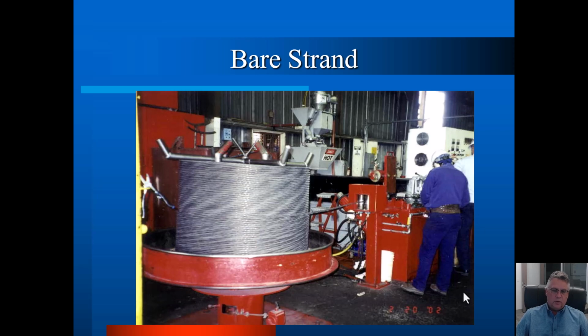So this is the Dywidag Systems International, or DSI, plant in Long Beach. They just need one big, large spool of half-inch diameter strand. And then they will take your drawings and cut to length exactly what your drawings require, the multiple different lengths that are necessary. So this starts off as bare strand.